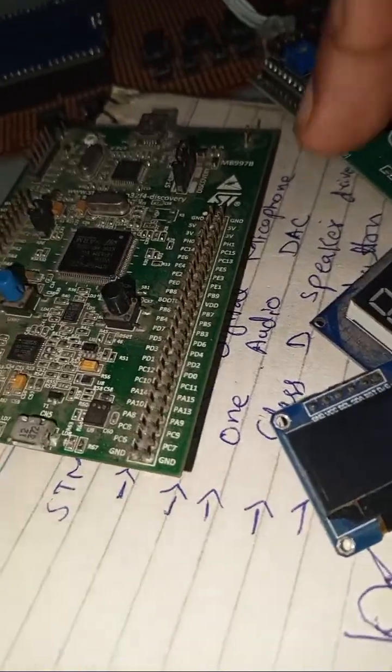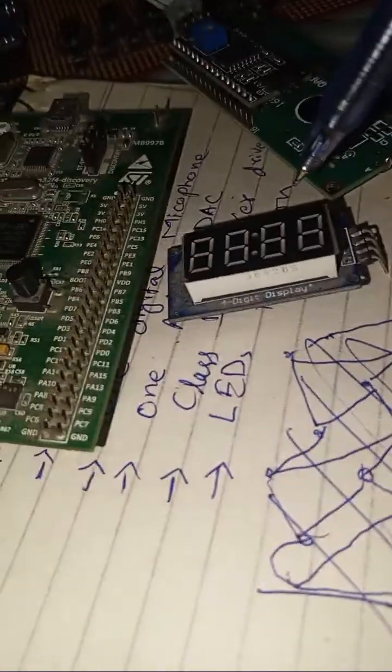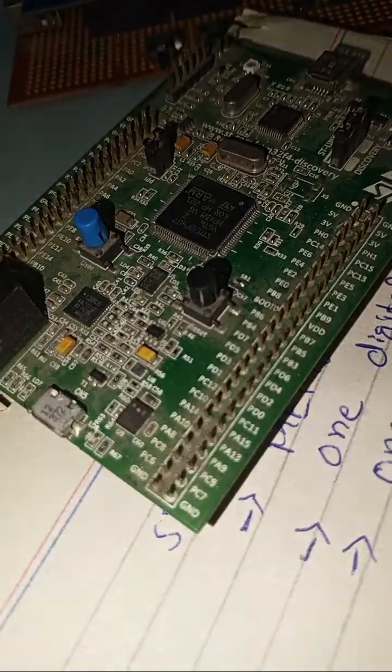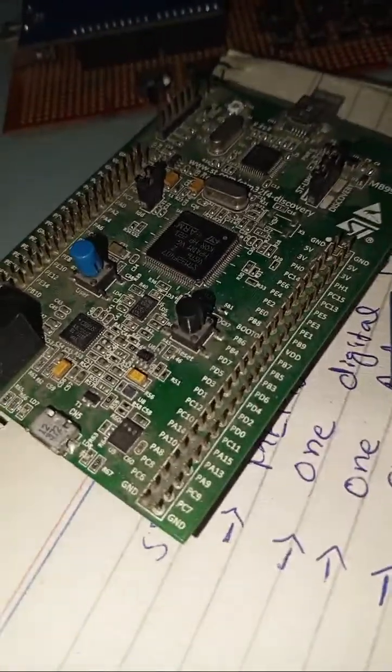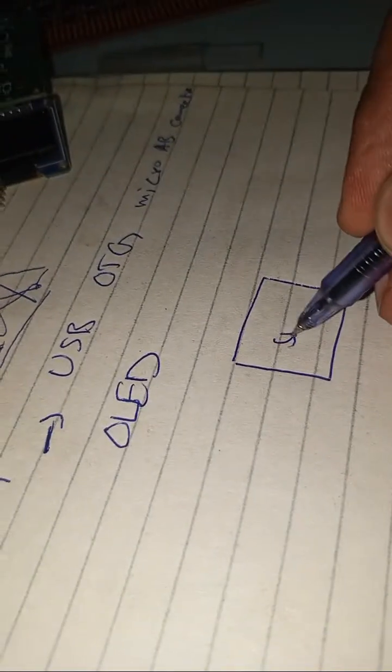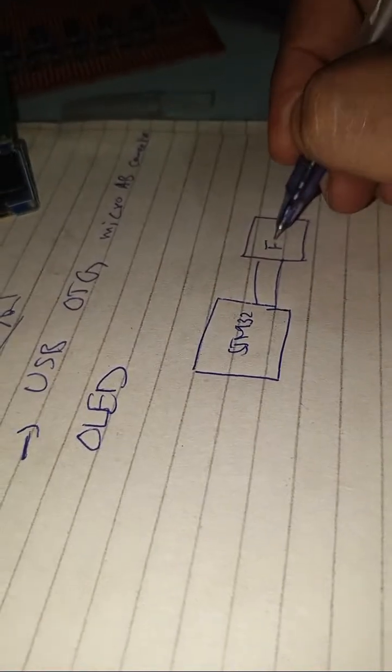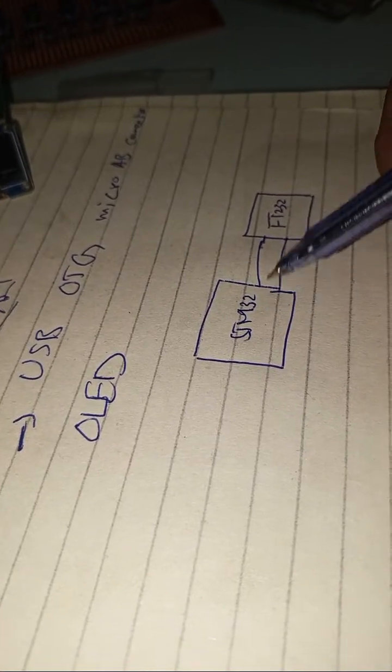But for the gesture recognition, starting with a simple display, for example, if we do some gestures 1, 2, 3, we use this, but we have to make training data as well. So what I'm thinking is, let's say I have this STM32, and I think there should be an FT232 chip for serial to USB conversion. So I send some data to the PC.